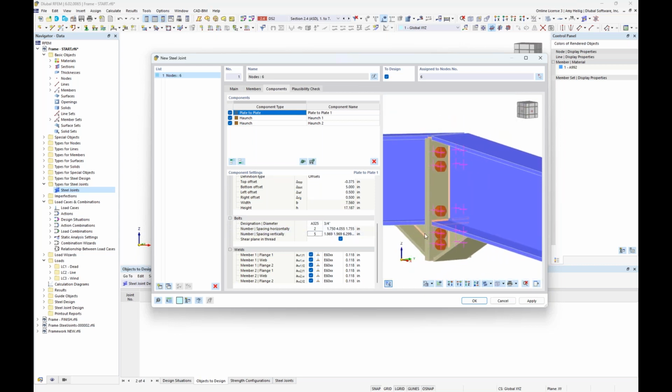Now, as far as the bolts in the vertical direction, currently we have 5 bolts, but I'd like to reduce this to 3 bolts instead. And obviously, once we update this, we need to adjust our spacing. So we have the vertical spacing. The first input option is going to be from the top of plate to the center of my first bolt, which will be 3.5 inches.